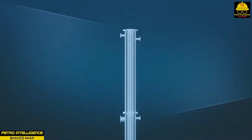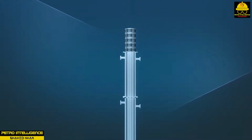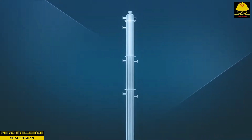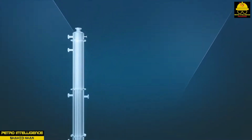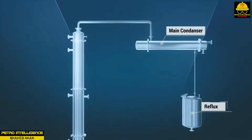The feed system is designed to safely store, blend, and transport the raw feedstock. This simple system is composed of tanks, pipes, valves, instrumentation, and pumps. Preheating systems are designed to raise the temperature of the raw feedstock before it enters the distillation column. Various heat transfer devices are available for the process. Typically, a heat exchanger or a furnace system is used.